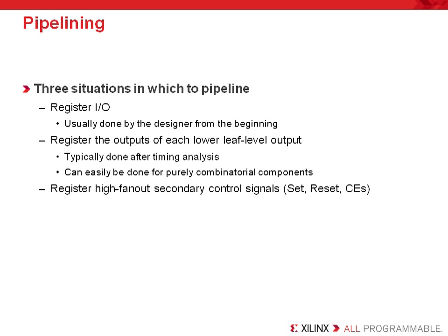Finally, high fan-out secondary control signals should be registered, and as we will find out later, it is important that you are familiar with all the control signals you have associated with your design. But since synchronous sets, resets, and clock enables are so common, you should always make sure that their source is registered. This helps assure that the long net delay can be tolerated and meet timing. Note that this is especially important for synchronous sets and resets because these paths are automatically covered by the period timing constraint associated with the Xilinx implementation tools.